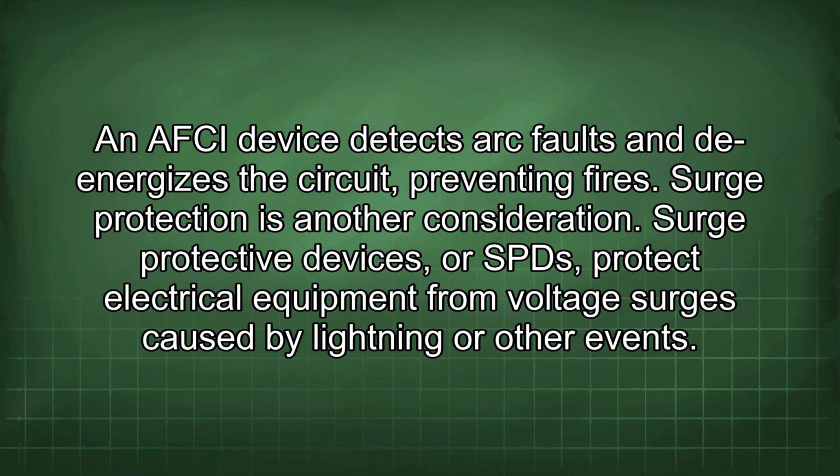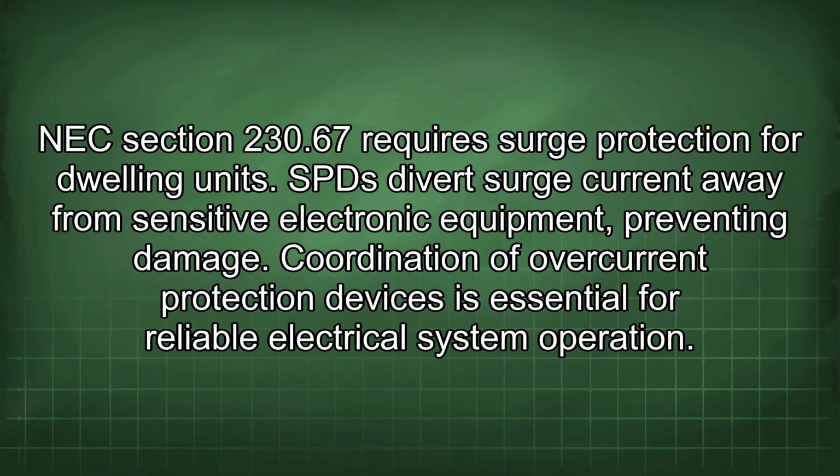Surge protection is another consideration. Surge protective devices, or SPDs, protect electrical equipment from voltage surges caused by lightning or other events. NEC section 230.67 requires surge protection for dwelling units. SPD diverts surge current away from sensitive electronic equipment, preventing damage.